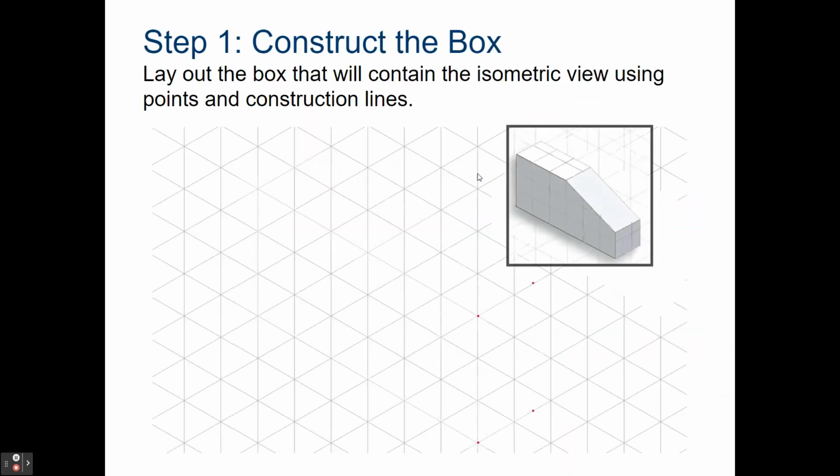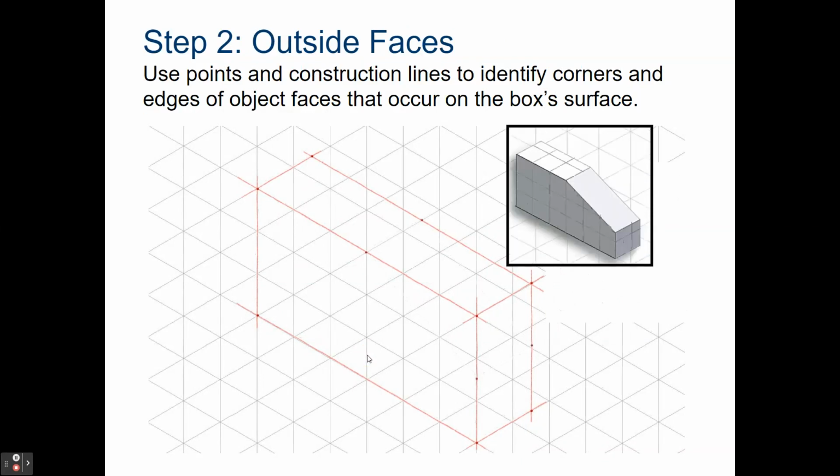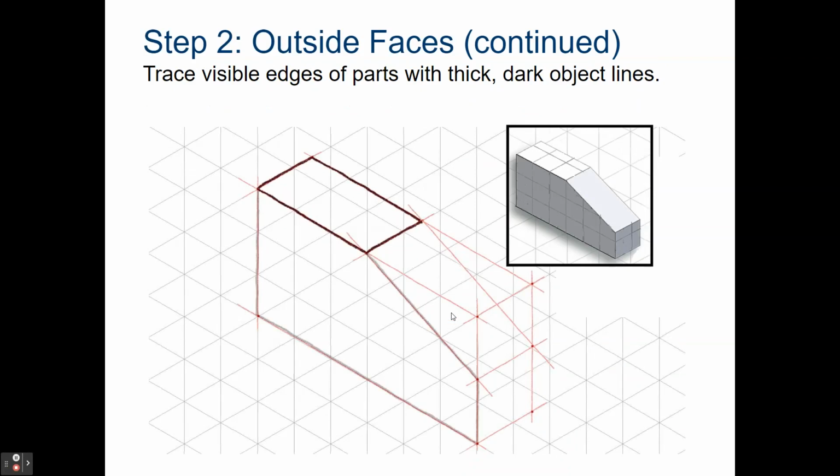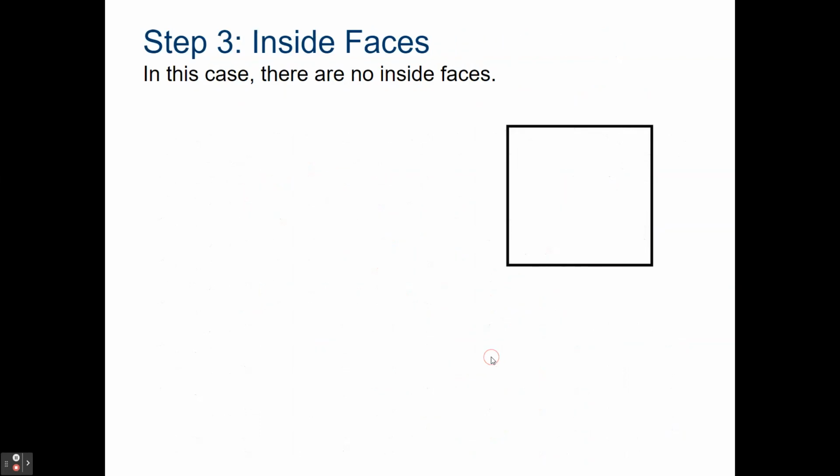And here's a bunch of examples for that. So here you have an object that you're going to sketch. By reading the number of grid squares that you see imprinted onto the object, we can kind of estimate its overall height, width, and depth there, and then frame out that glass box. And then really we just have to have this little chamfer cutout so you can see the points here that are identified on our construction lines. And we will go ahead and connect those on a diagonal. And then from there, we actually have everything we need to start drawing in object lines and darken in the features of the part. And that would be it.